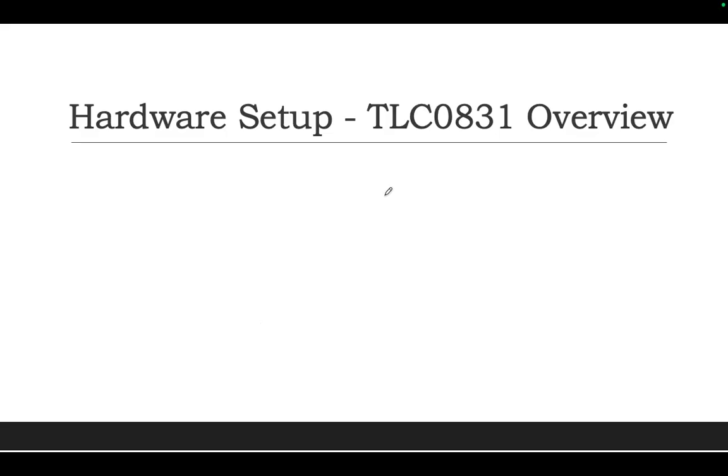Yeah, that's true. What's the main function of this chip? Analog to digital conversion. Yeah, it reads the voltage and converts it to a binary number, which is then read by the Pico. It is an 8-bit ADC, and it is MSB first.